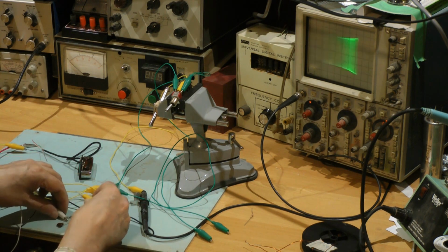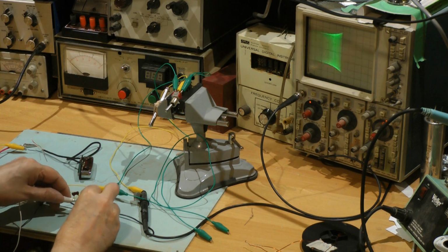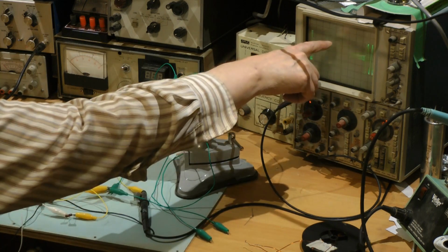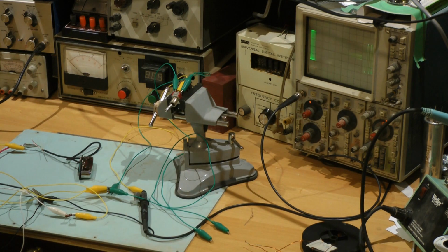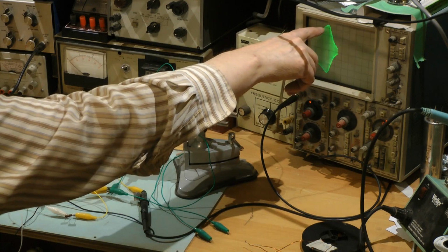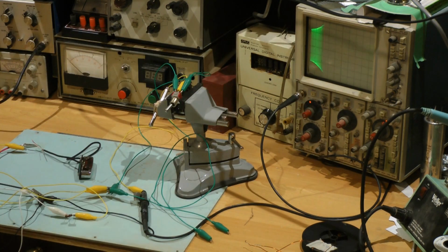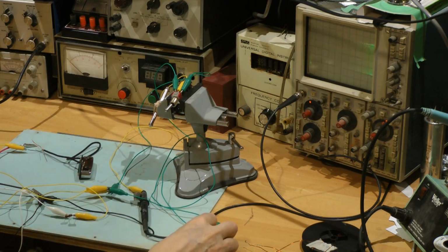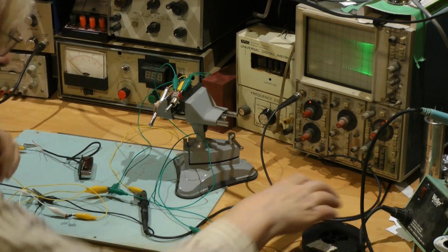Okay, I'm going to add in 470 picofarad. You can see it peak. It's the same peak we noticed on the spreadsheet. That would represent the 6-foot cable. The highs are really cut down. We got a peak up here. Okay, I have a switch in here with some leads and I can add in some stuff.